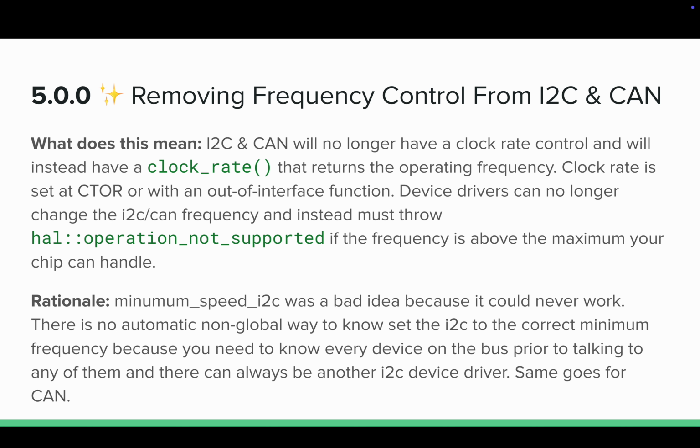And then UART also, because there's only one device that should ever use UART. It's basically once you pass it to something, that something owns it forever. It'll still have a baud rate control because it basically just allows the driver that you pass it to set the baud rate to what it needs, and that throws an exception if it's not supported, which is what we want. So that is basically the last item here until we go to next week.